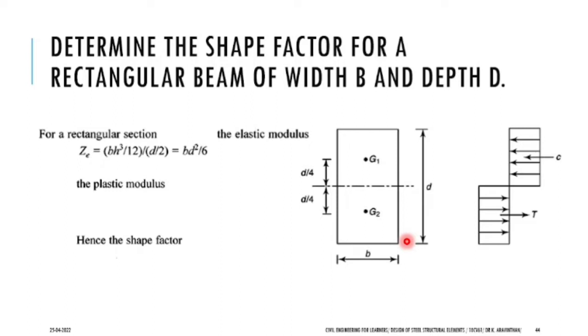The same material, the same concrete you can put, but if you change the shape, what happens? The moment of inertia changes. So in certain areas it can take more load, and in certain areas it will take less load. What happens if you have a rectangular column?